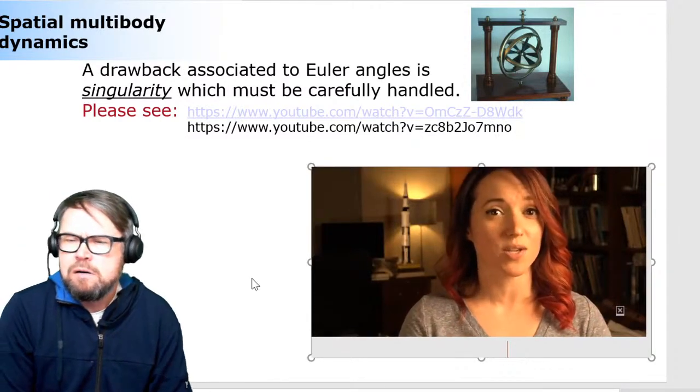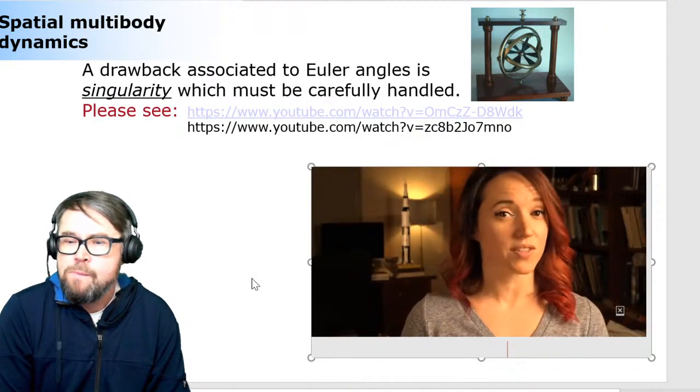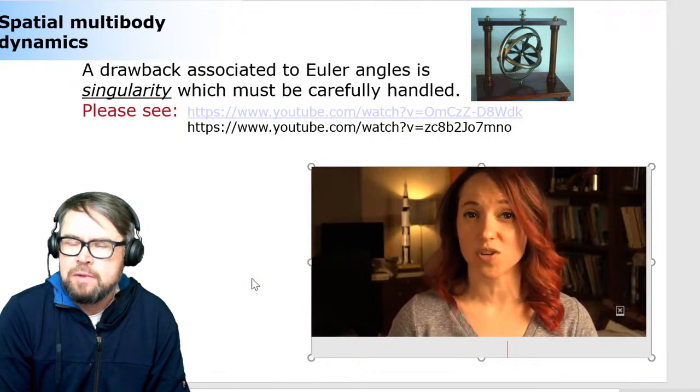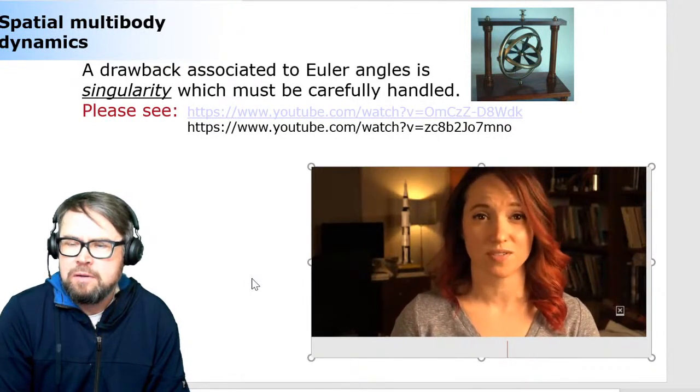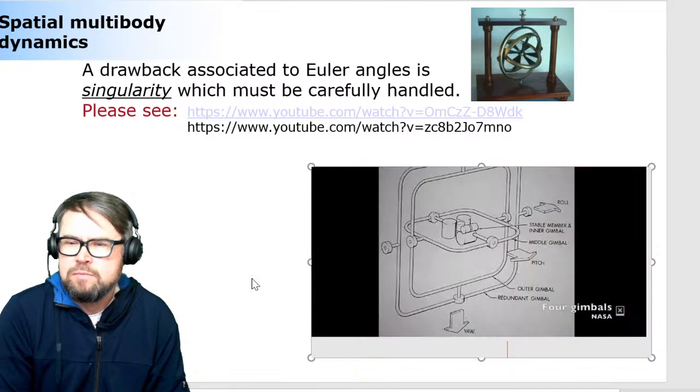Explosion. And that is why you hear in the movie and read in the transcript astronauts yelling about watching the gimbals. Losing their attitude in space would have made the entire situation on Apollo 13 just that much worse. The simplest way to avoid gimbal lock would have been to add a 4th gimbal into the IMU, just giving it another reference point so that the gimbals wouldn't be able to align the same way.